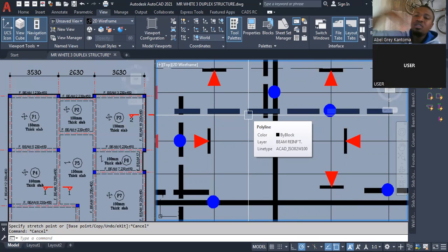By the time you return your reinforcement like this, if you don't place those distribution bars on it, it will definitely be flappy like this. So there's no way it can stand. And if you check that top distribution bar, it always goes just like he said. It gives it stability around there. It will hook inside your reinforcement from your beam, go inside and then return back. Then that's your reinforcement that returns, I mean. Then you now have your top distribution bar at the top of that return.